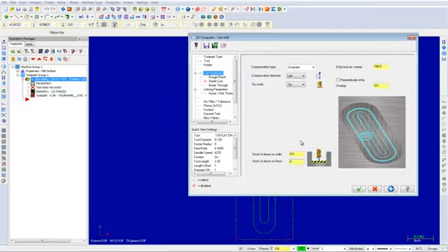Computer sets Mastercam to compute the compensated toolpath and does not output control codes for compensation. Entry exit arc sweep sets the included angle of each entry and exit arc. If the entry exit arc sweep is less than 180 degrees, the system applies an entry exit line. Perpendicular entry enters the toolpath perpendicular to the first tool move.